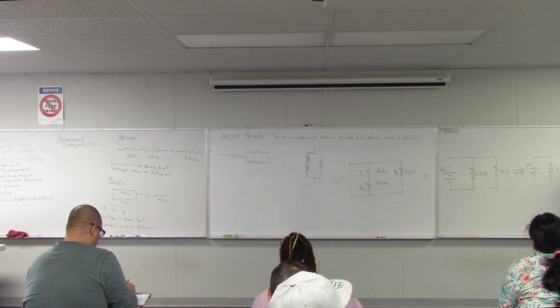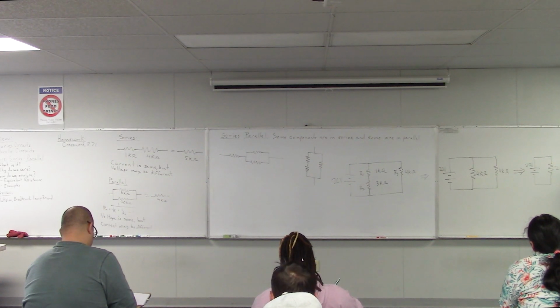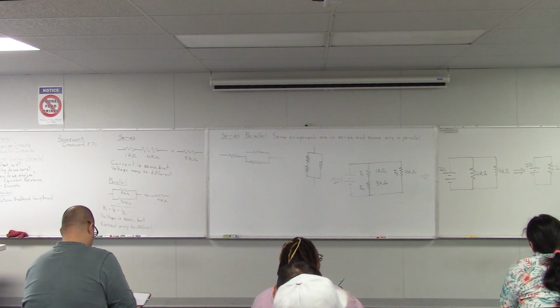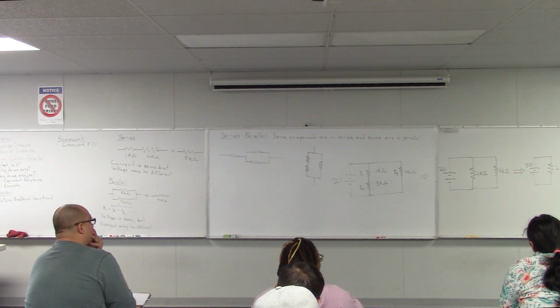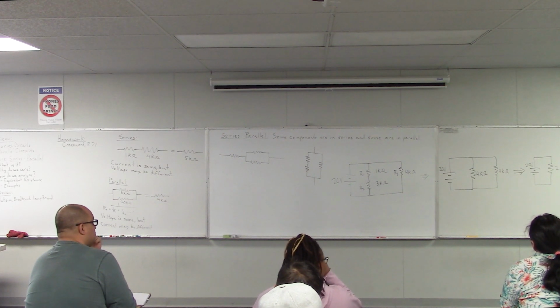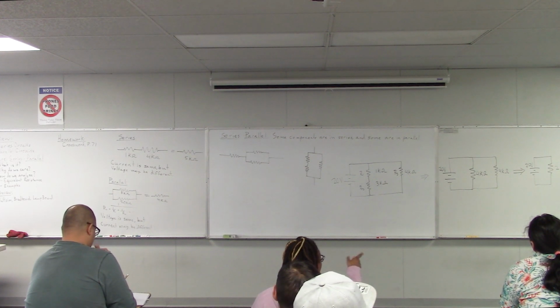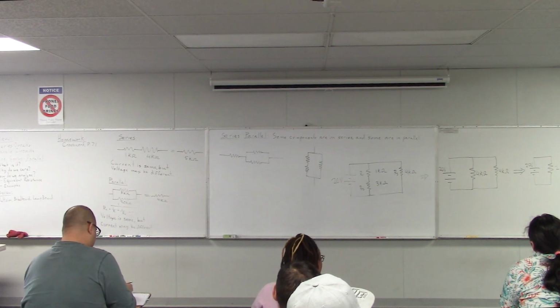So remember, Ohm's law is like this. We've got V, I, and R. So if we want to find the current, we write down I equals, we cover that up and see that it's V over R. So that would be 20 volts over 2 kilo ohms. Now, can I just say divide 20 volts by 2 and get a total of 10 amps for this whole circuit? No. No, exactly. And why not? Yeah, because of the engineering notation, the kilo ohms. Right, exactly. This isn't just 2 ohms, this is 2 kilo ohms.